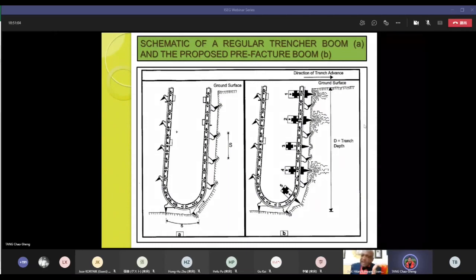The one on the B is my design, where we would have some impactors hit at particular points on the boom. Those are hammers that you see there. The hammers are designated with 1, 2, 3, 4, 5. Those hammers would be hydraulically operated or pneumatically operated. That is, pneumatic operation is with air, hydraulic operation is with oil.